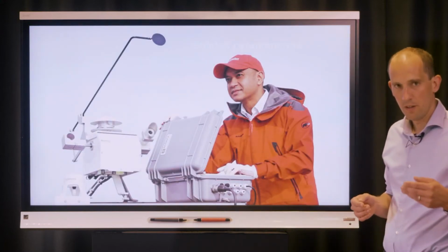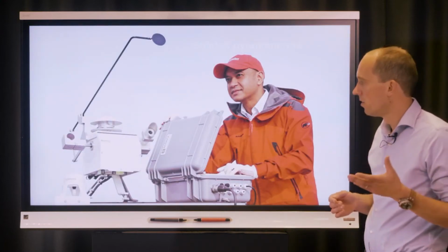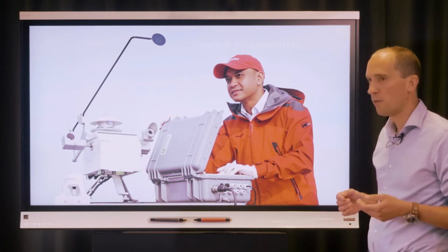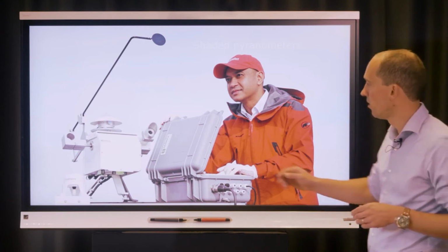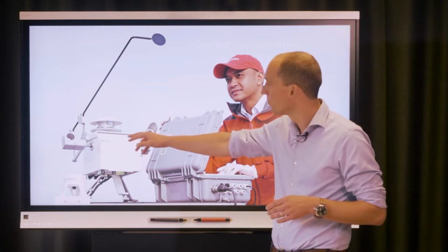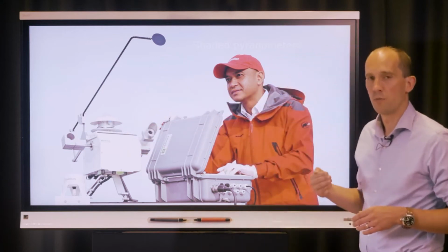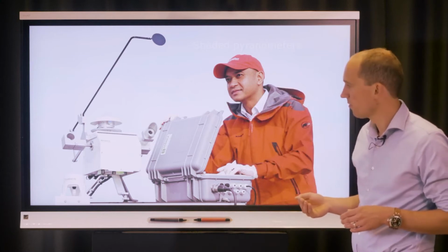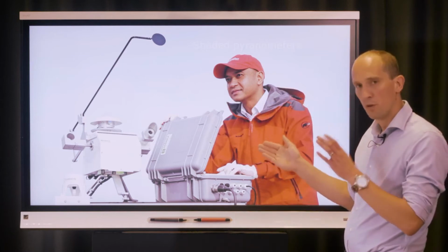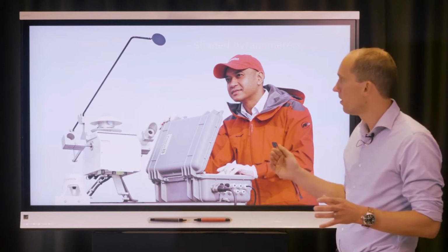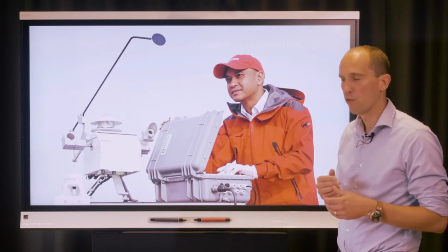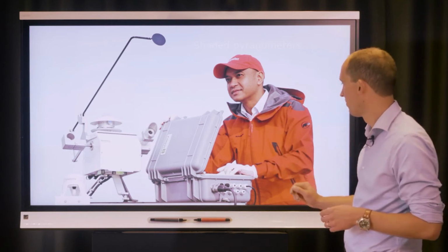And here is an example of how you can use a pyranometer to measure diffuse radiation. You see the pyranometer is on the solar tracker, and there is a shading disk which blocks direct sunlight from reaching the pyranometer measuring surface. And as the sun moves, this tracker will move, and also the shading disk will move, keeping this instrument continuously shaded.